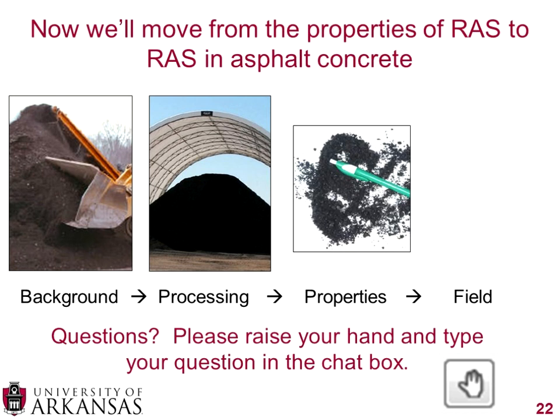And I think that's an excellent question. So if you know a soft binder grade, and you blend a harder binder into there, and you get a new binder grade, assuming it's a linear relationship, you start getting on kind of shaky ground because asphalt cement's not a linear material. The properties don't change linearly with time or temperature.